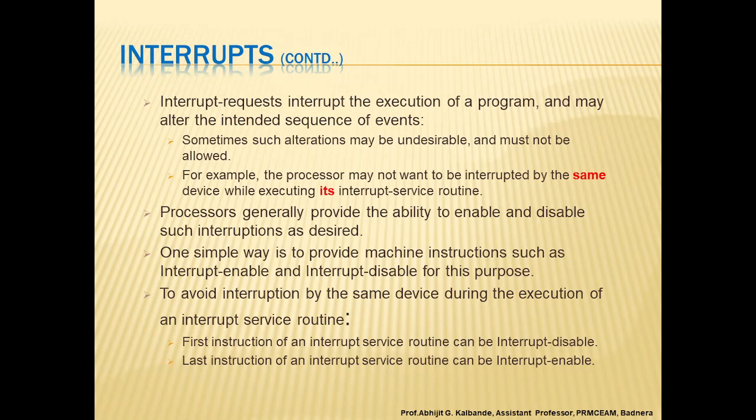Most modern processors save only the minimum amount of information needed to maintain the integrity of program execution. This is because saving and restoring registers involves memory transfers that increase the total execution time and hence represent execution overhead. Saving registers also increases the delay between the time an interrupt request is received and the start of execution of the interrupt service routine. This delay is called interrupt latency. In some applications, a long interrupt latency is unacceptable.